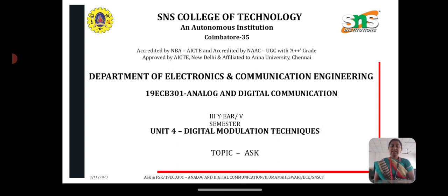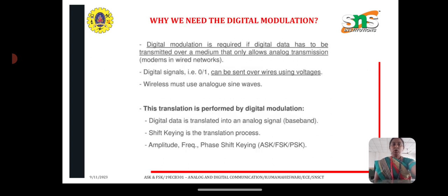In this video lecture series, I am going to explain about the digital modulation technique, which is amplitude shift keying. First of all, we see why we need digital modulation. Digital modulation is required if the digital data has to be transmitted over a medium that allows only analog transmission. In a wired network, digital signals, that is zeros and ones, can be sent using voltages. Wireless must use analog sine waves, where this translation is performed by digital modulation, in which digital data is translated into an analog signal.